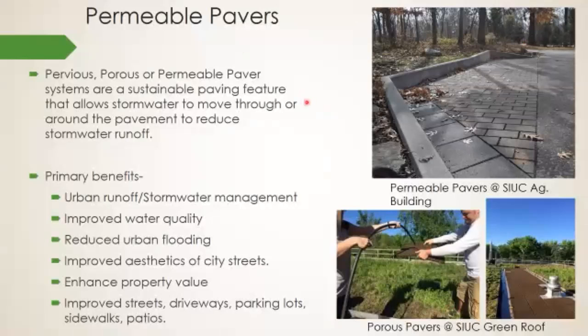One good example, and one of the main reasons this permeable paver section was built, is at Southern Illinois University Carbondale, where we've gone on tours of these other green infrastructures, and we'll do a quick demonstration and tour of this one today. The main issue was that to the right, which you can't see, there's mostly hardscape. There's a very large college building there, the College of Ag, and it's flat roofed. And then we've got a lot of walkways. So there was water pooling along here against Thompson Woods, sometimes almost a foot of water standing where people would be. That's a major thoroughfare of foot traffic, so that was a big issue that needed to be managed and addressed. And this was the way to do that.